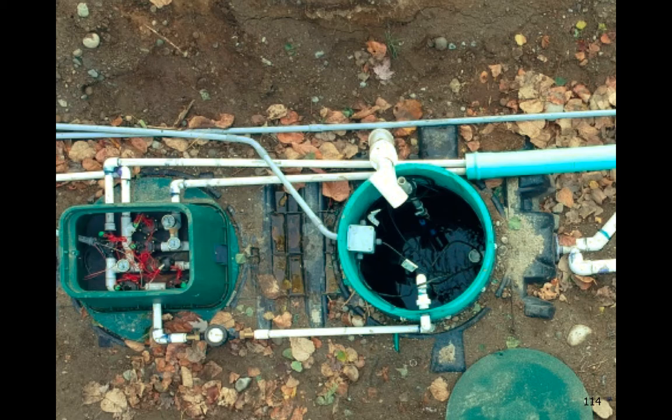This is an aerial photograph of how we would suggest putting the Headworks in place. This is an infiltrator tank. We're looking down in the recirc tank. We come out at a 90-degree angle with our pump line, elbow over, go plumb in our flow meter, and then elbow again into our Headworks.